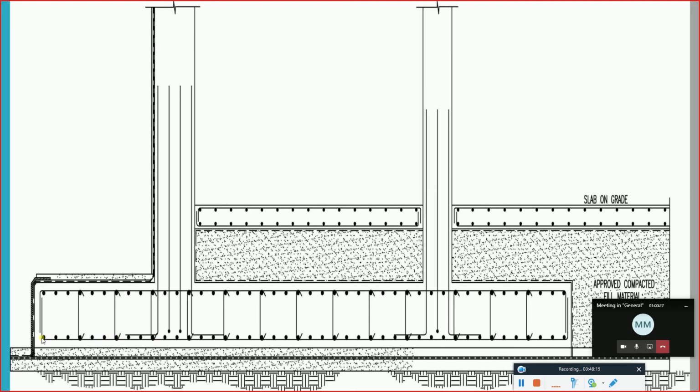So what we need to do normally, we provide reinforcement for the bottom according to the bending moment, and then we provide top reinforcement according to the top bending moment. Now, one person will say that normally in slabs we don't continue doing the top reinforcement. I'll say normally the distance between the supports for the slab are far away from each other. When it comes to the foundation, the distances are not very far from each other. Okay? In case they are far, the reinforcement will not go in this way. It's going to be more into isolated with bottom reinforcement only.